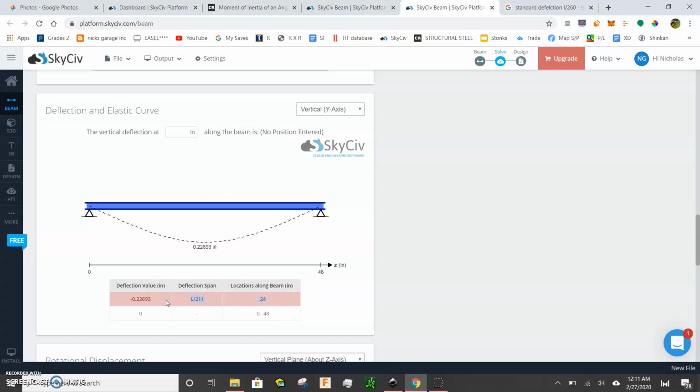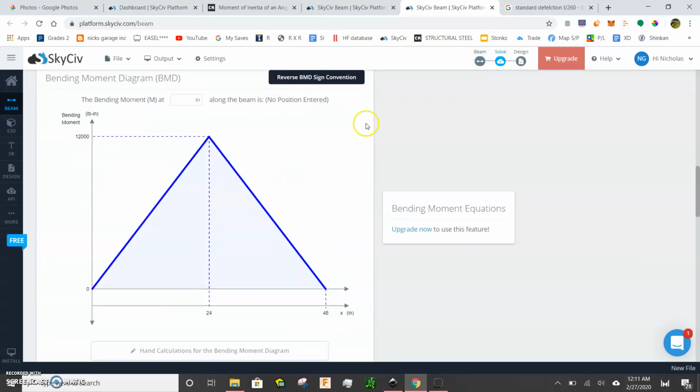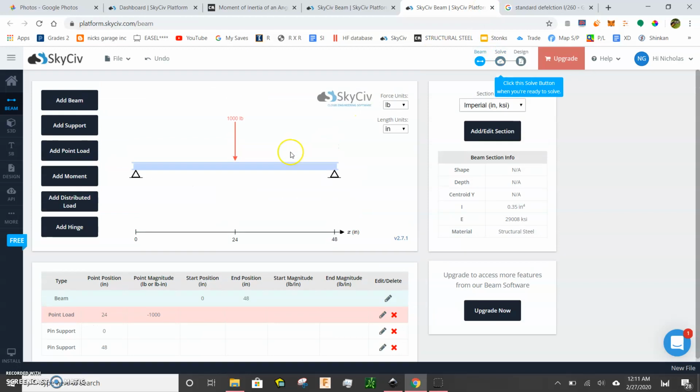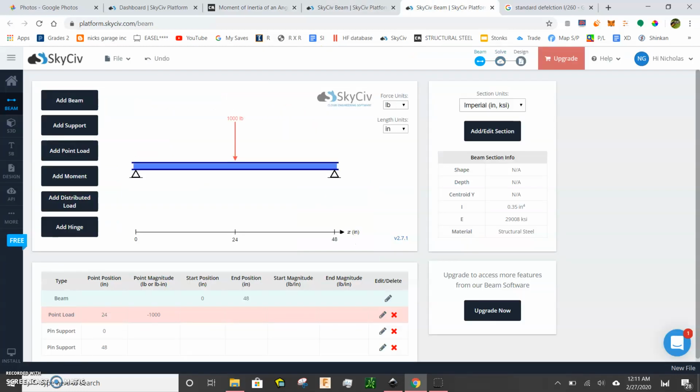So obviously we know this would not be safe to run on the road because the beam would deflect too much and it would not meet the spec. So that tells us we need a thicker beam, or we have to put less weight, because this beam will fail. It's not rated for that by the standards. So then you would say, okay, maybe let's try 3-inch angle, right? The IX, moment of inertia, is 0.24.